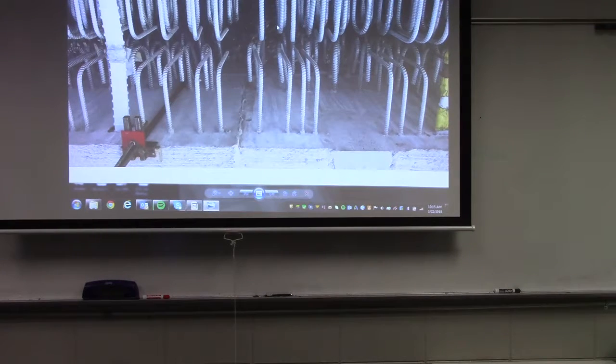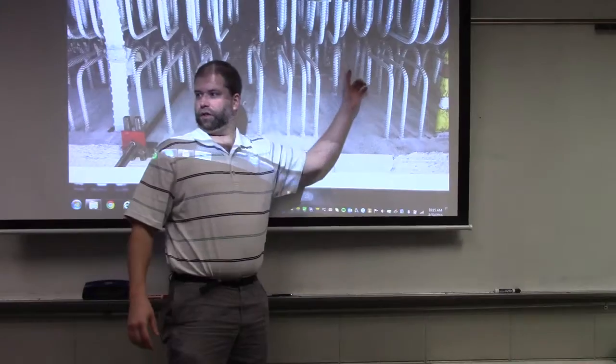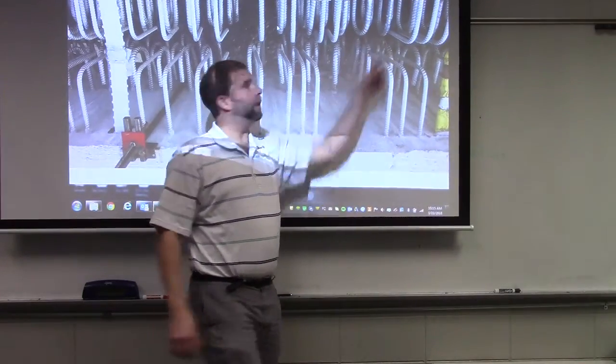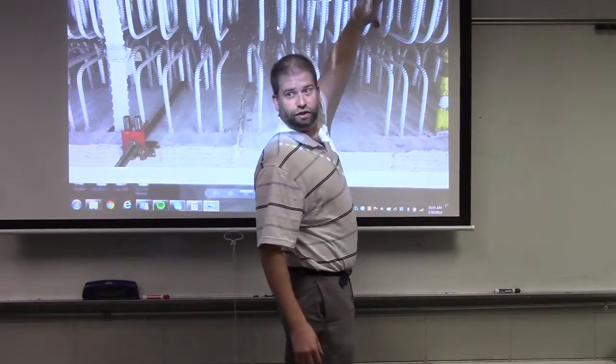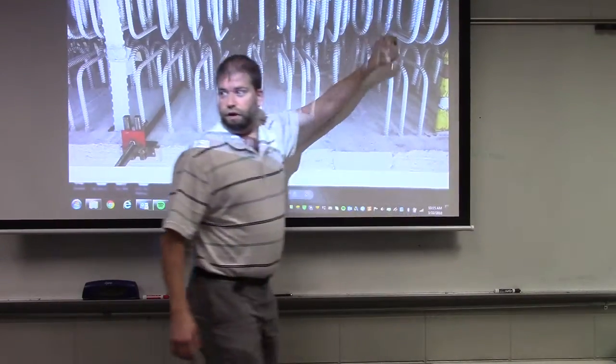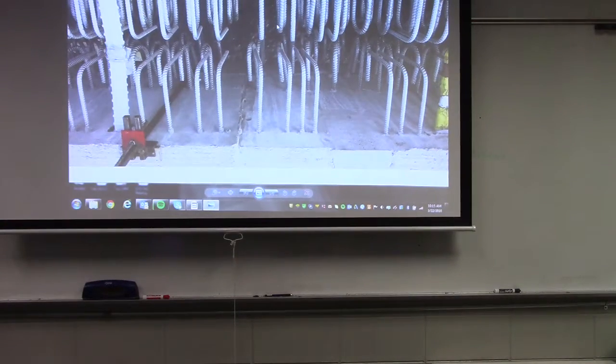You maybe could have. The problem, I think, that they're gonna come into is you need a certain amount of development length to get the strength. They're increasing it with the hooks, okay, because instead of having just this much development length, now they have that much development length for their rebar themselves. You can reduce your development length a little bit by increasing the strength of the concrete.